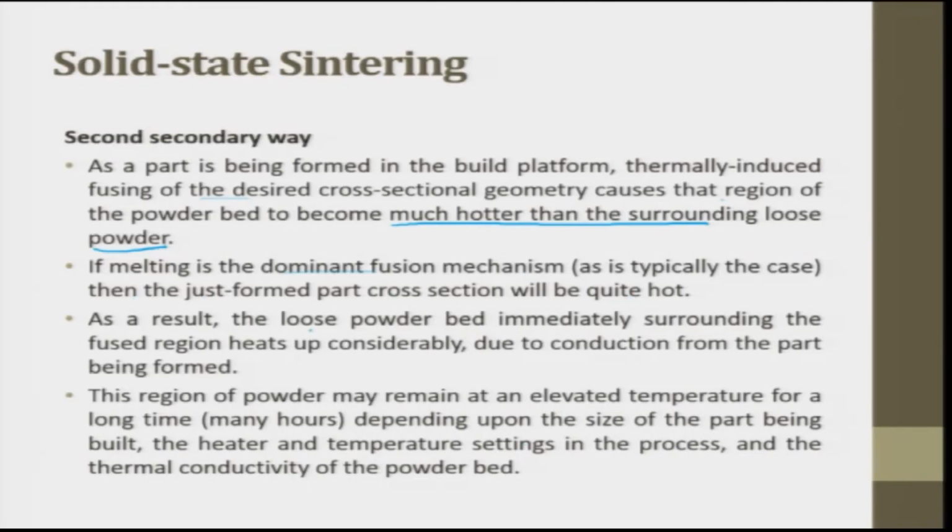As a result, the loose powder bed immediately surrounding the fusion region heats up considerably due to conduction from the part being formed. This region of powder may remain at an elevated temperature for a longer time depending upon the size of the part being built, the heater and the temperature setting in the process, and thermal conductivity of the powder bed.